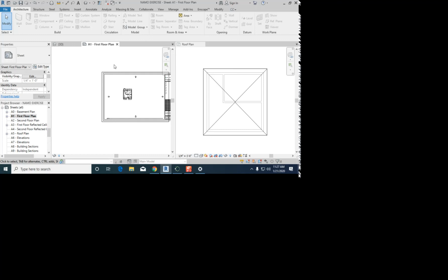We can make sure it's applying to all the levels. Yeah. So we can see how that change affects something else. Absolutely. So despite it being cool, really that's the answer I'm looking for. But you can see immediately, wait, I drew a roof level, but my walls are going unconnected up to 20 feet. Or for example, Olivia, if we started with something that wasn't a generic wall, you would have immediately been able to see that your bricks were on the interior and not the exterior, right? So it also lets you quickly visually identify what you're building as well.